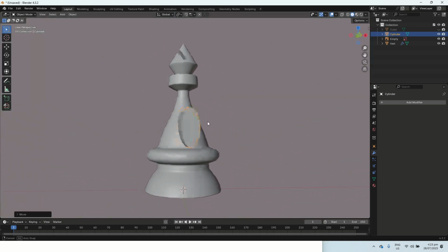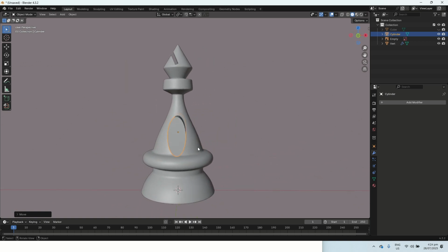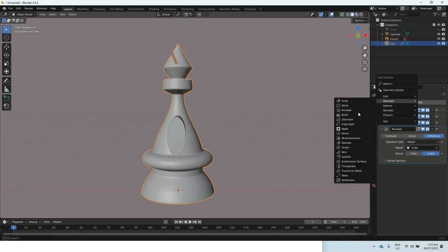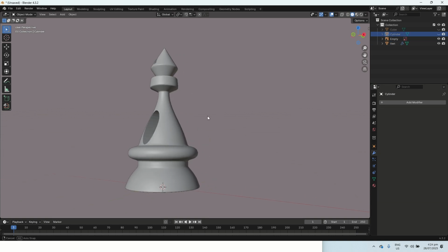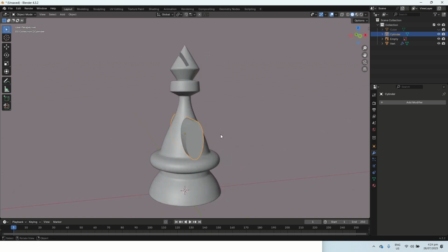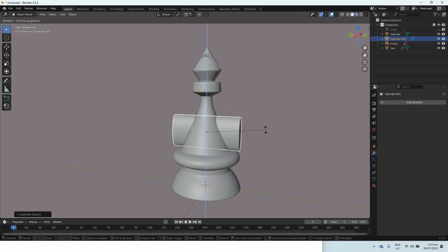So this isn't going to be super pretty. This is just sort of an example. I can take something like this shape here, and I can add another boolean. A hole straight through it, that's right. Okay, so something like that. I can do the same coming from the other side. So maybe we can just duplicate this. Shift D to duplicate. RZ90.